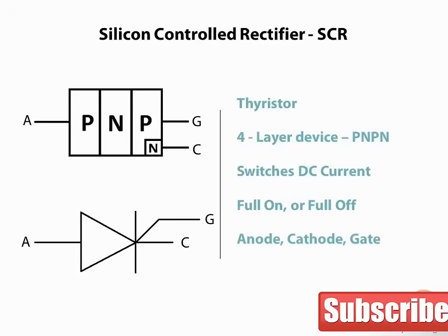A small gate current on the SCR will cause it to conduct. Once the SCR conducts, removing the gate current does nothing. The SCR switching action is latching. In order to interrupt the current from the circuit, power must be removed in order for the current to stop.